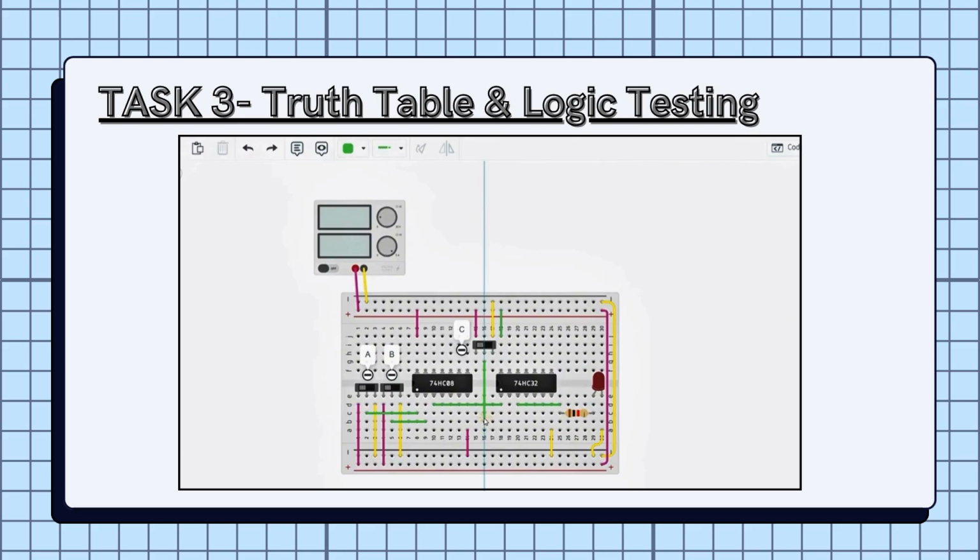When the power is on, the LED lights up when both A and B are on together, or when C is on. If none of these switches are on, or only A or B is on alone, the LED stays off. The simulation tests all possible combinations of the three switches, as shown in the truth table.